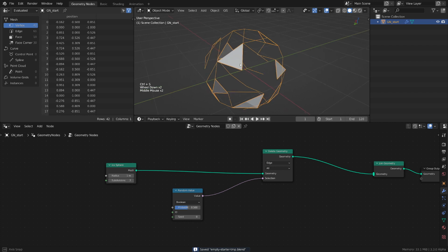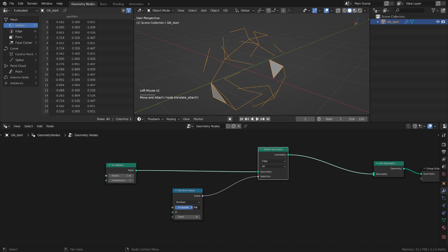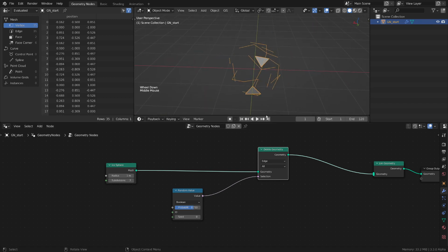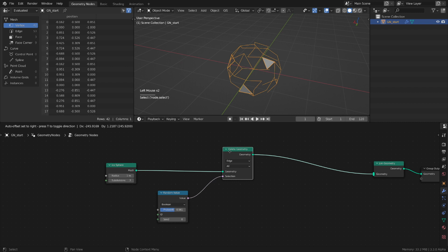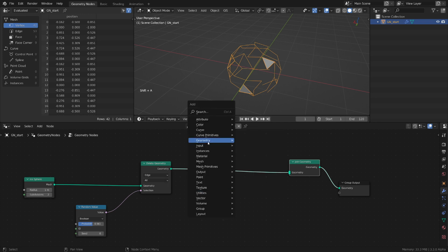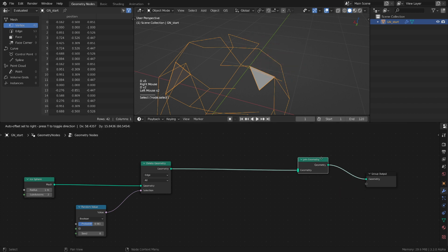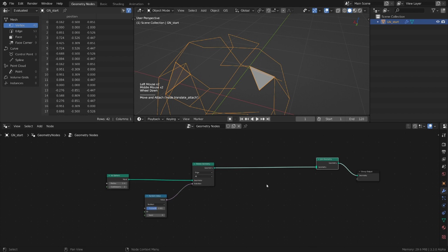But don't worry about these faces that are here. It's gonna be easy to get rid of them. But first, let's just decrease the number of lines, because we don't really need so many. We can even leave these faces for a while so you can see what happens. First and foremost, we don't really need a mesh. Now we have a mesh here. But what we actually want is splines, because later on we want to have an easy way to track those lines, and spline curves offer you a much better way to do this kind of thing.